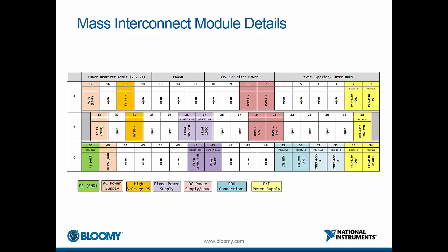Here we show the system connections for a custom power module. This particular module is a 50-pin micropower with contacts rated to 21 amps. There are 3 rows of contacts laid out as shown here. Each block corresponds to an individual contact of the module, and the information about the connections and signals are provided for each populated contact. It is important to document your module pinouts in an intuitive way, as they will be used often when designing your fixtures and debugging your system.